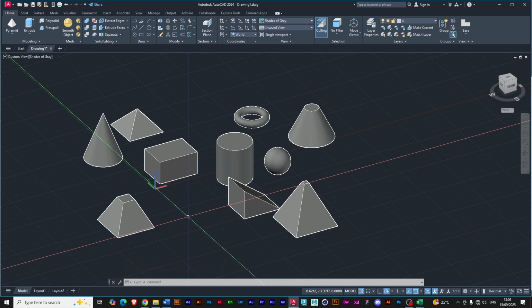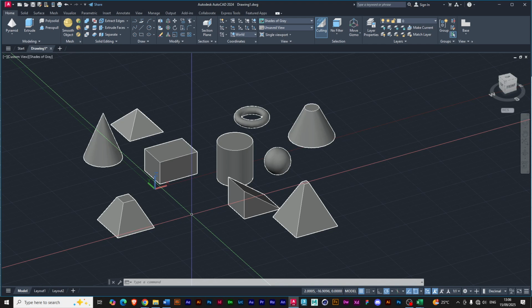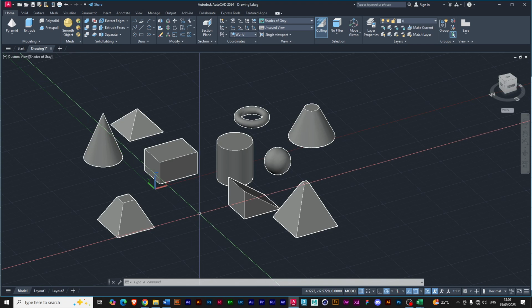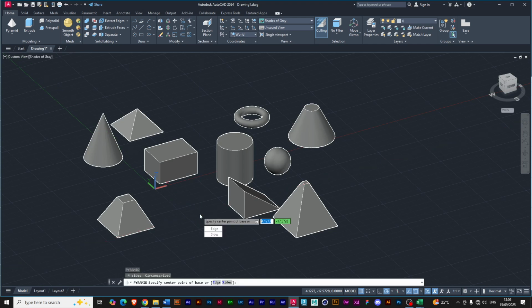Now for us, we did one setting last class, that Enter setting we did with the right mouse click. Right now nothing is selected. If I press Enter or click my right mouse button, it will take me to the last tool I used while I was drawing.